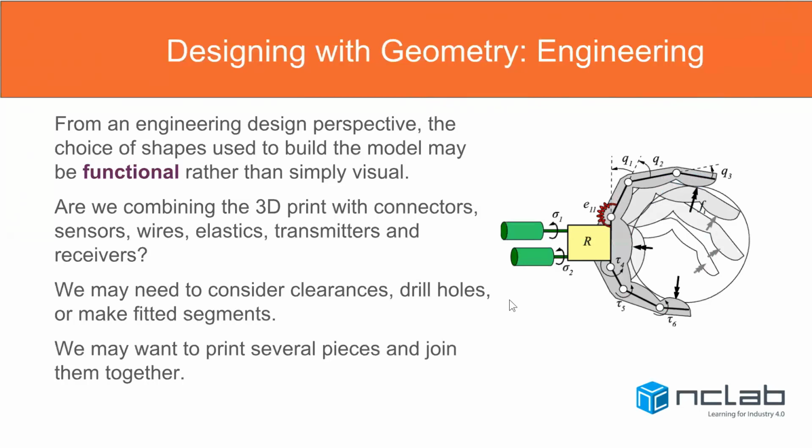And remember, we're talking about SLS. You might lose the hole. Actually, I think all the processes are a little iffy on holes. You need to clean up your print usually afterwards. You may be looking at fitting pieces together very closely, so you're drawing your dimensions very carefully. Again, you might be printing several pieces and then later joining them together. So keep that in mind, that engineering looks at design a little differently than just visual.